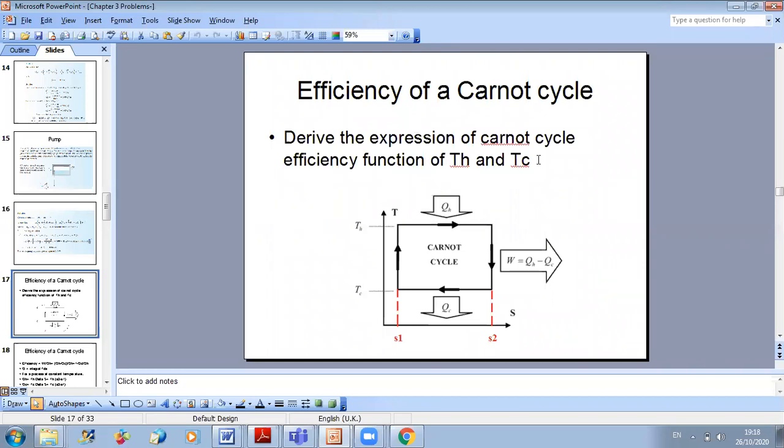I want to give you an additional note. We said before that the total work of a closed cycle can be calculated by the integral of PdV. If it's a moving boundary, we use the integral of PdV, and if it is a fluid circulating in our system, we use minus the integral of VdP. But at the end, both represent the area under the curve of P as a function of volume or V as a function of P.